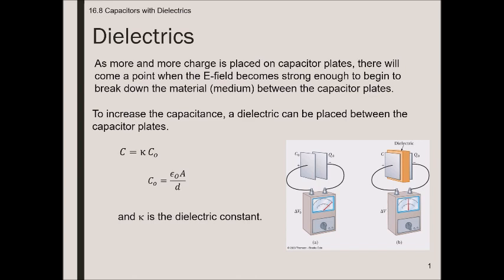We're going to talk a little bit more about that in a second, but what the dielectric does is it basically adds a multiplier. So we talked about this base capacitance, which is why there was a naught on there. That assumes that basically there's air, but the full formula is really the capacitance is equal to this dielectric constant K times epsilon naught A over D. I'm not sure why they don't include the K from the get-go, but that's the way it's done in every book I've looked at. So this K value is the dielectric constant.